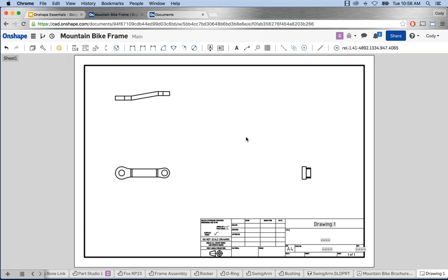Of course, the toolbar is different. So you have your drawing views, you have your dimension tools, your annotation tools, the things you'd expect to see in your drawings. A question that's come up: is mirror available in an assembly? And the answer is no. We do have a replicate function that gives you similar behavior, but mirror itself is not available in assembly.